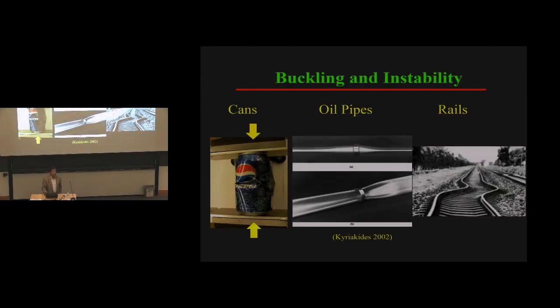I know many of you are engineers, and many of you took solid mechanics or mechanics of materials, right? So we talk about engineering structures. There are always two types of problems. One is a failure, like a break, right? Damage. Another type is called a stability issue. So things can lose stability under certain load. For example, if you have a long bar, actually I have here examples of rail structures, like the rail during the summer, right? Too hot, so the rail can buckle, loss of stability.